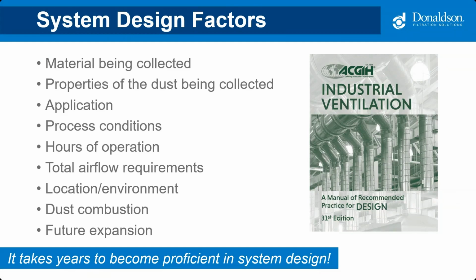Things that we need to consider when designing a system include the material that's being collected and the properties of the dust being collected, the application being utilized, the process conditions. Is it humid? Do the workers use personal fans? Does the facility have conditioned air? What are the hours of operation? Will the system be used continuously or intermittently? What's the total airflow requirement? What location or environmental restrictions exist?